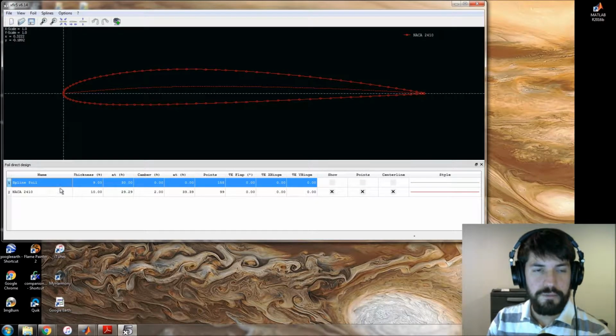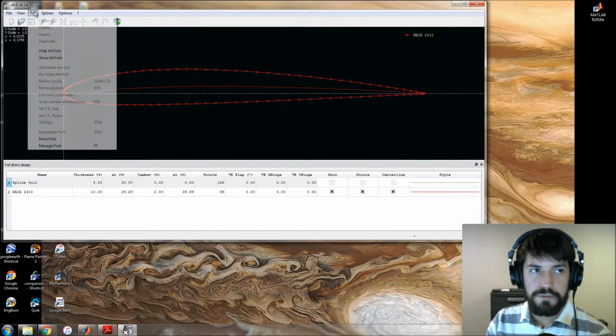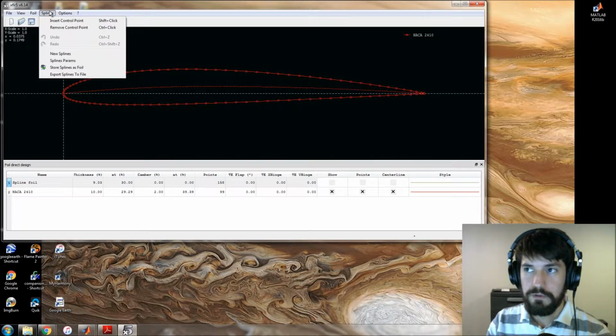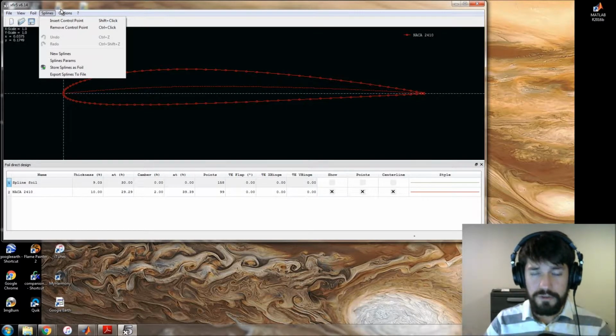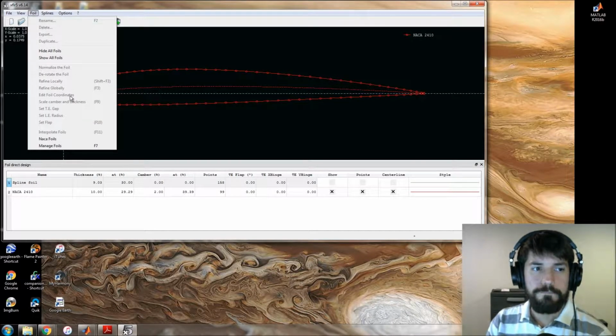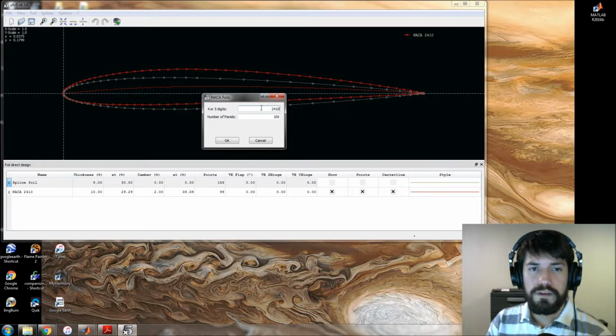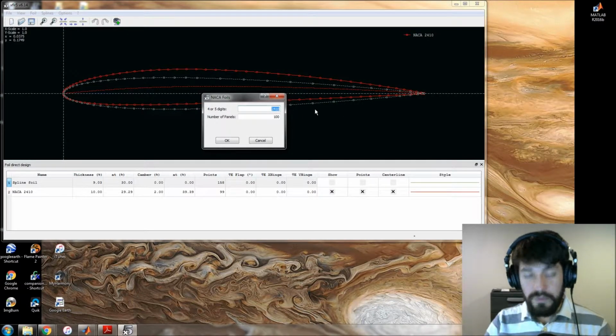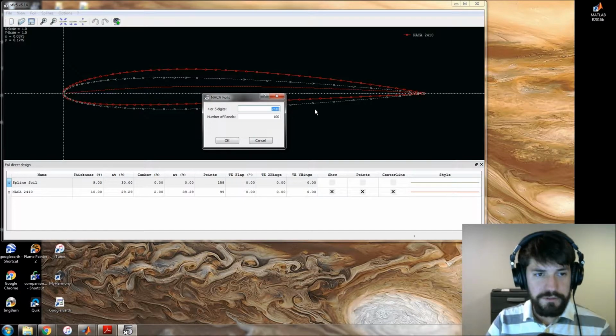So just as another example, if you want a symmetrical airfoil, which you should use a symmetric airfoil for any stabilizers in your analysis, horizontal and vertical stabilizer. I'm talking about the tail surfaces in the back. Or if you have like a delta wing or something, you might not necessarily want camber. I'm actually going to be doing a delta wing, so I'm not interested in that.